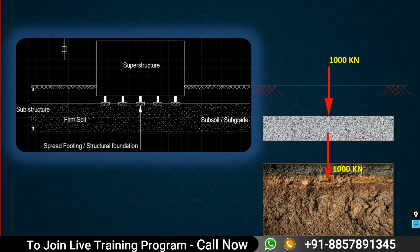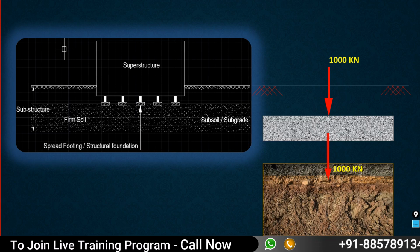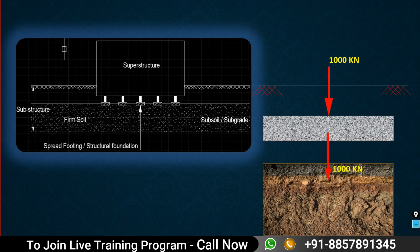So foundation plus subsoil combined give you the substructure. We are not designing the foundation to carry the load of the superstructure; we are designing it to transfer the load to the subsoil. So giving the subsoil importance equal to your foundation is very important.